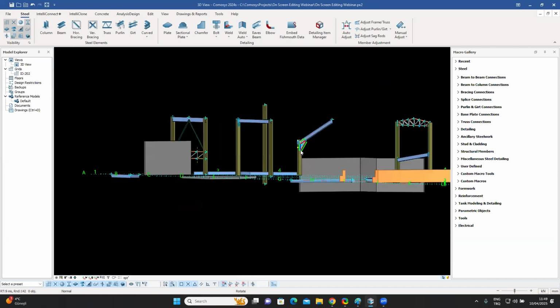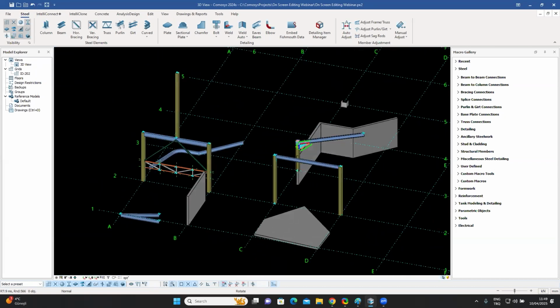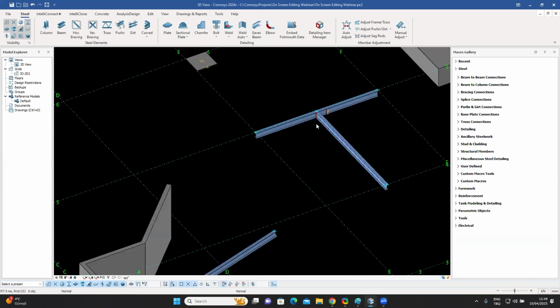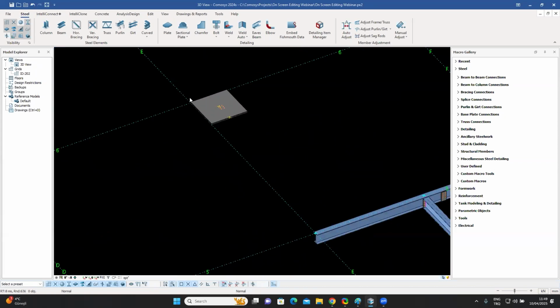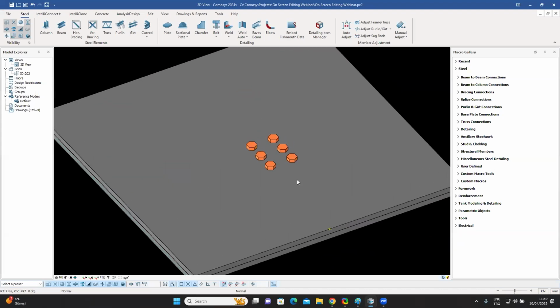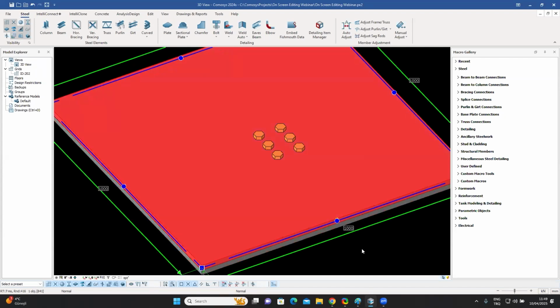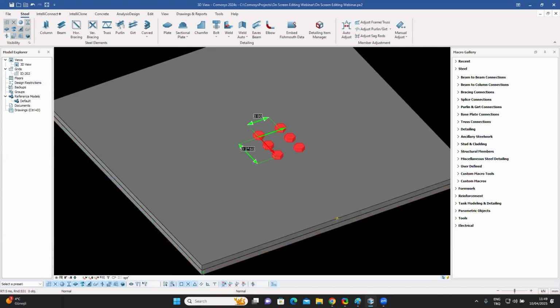Let's move on to some bolts, for example, over here. I want to talk a little about bolts. So one feature which we have right now is that the bolts also have their handles now. So if I select a bolt, there are two plates over here, and they've been bolted together. If I select a bolt, one thing I see is the control Q, which was used for rotating profiles, is available over here to reverse the direction of the bolts. So I can use my control Q to reverse the direction.